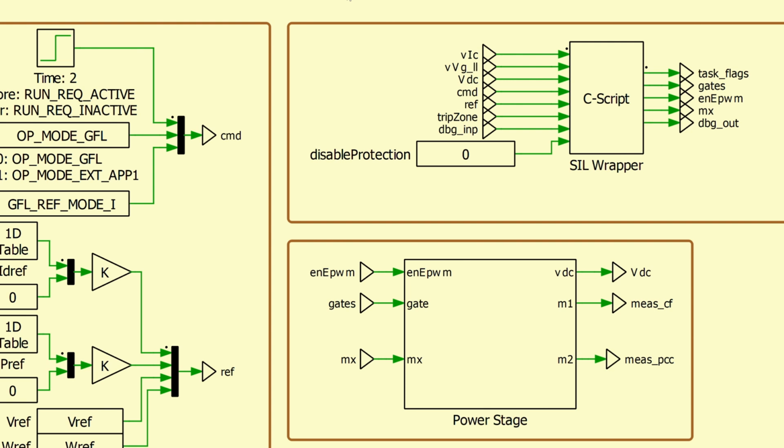If the software trips due to the protection in simulation, just like it does in the hardware, then the developer will not be able to debug the controller as it does not continue to run. Disabling this protection will allow the user to see the behavior of the controller so he or she can understand when and why the controller is tripping and